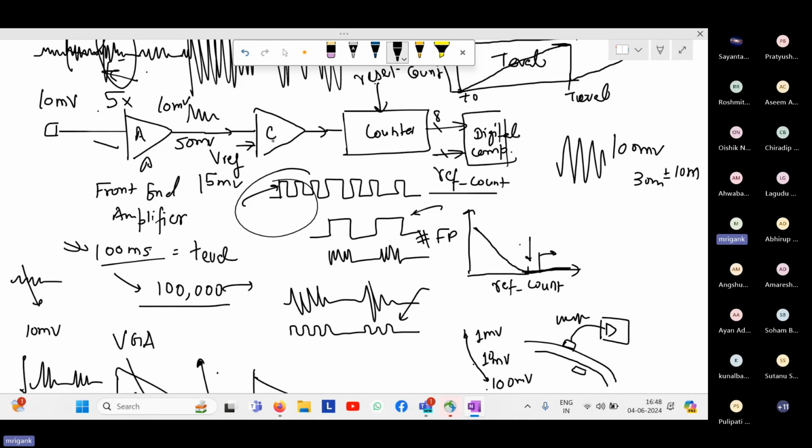In this case, the analog block will require a regulated power supply, with very little noise. So that will require an LDO to operate. And the counter and the digital output will require a clock. Generally for this application, the clock frequency may not be very high. As we mentioned, as one example, at max we are going for a count of 1,000 and the duration of the count is say 100 millisecond. So we may not require a very high frequency clock. At max, a few tens of kilohertz to 100 kilohertz clock will be good enough.